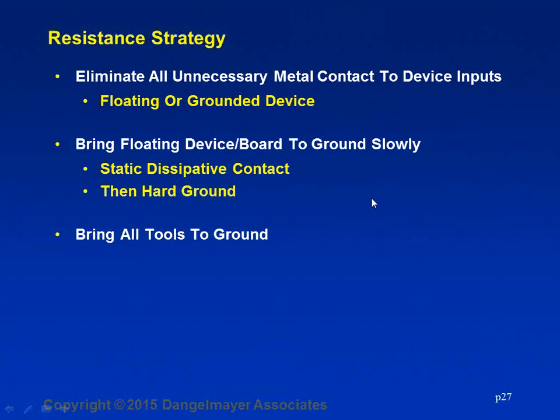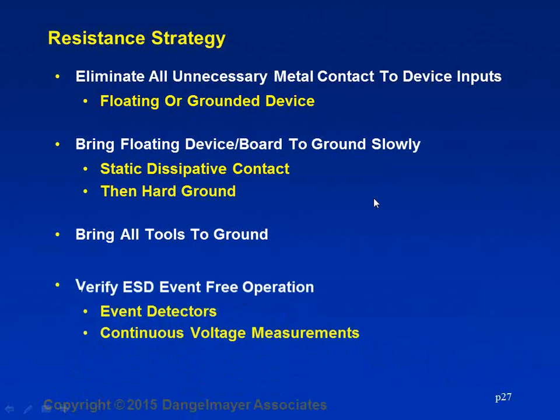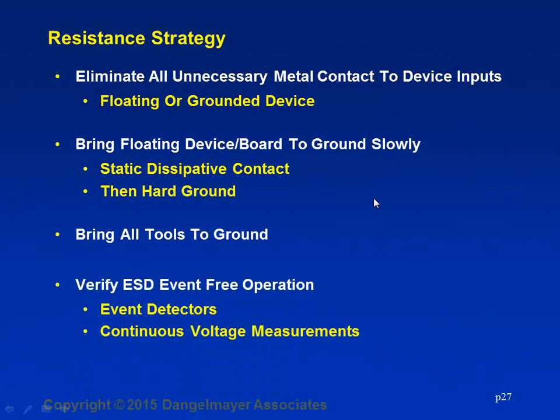Bring all of your tools to ground prior to contact. And then verify all of this is working effectively with ESD event detectors. This is a viable strategy to verify initially and also for ongoing process management to make sure that your product is not being stressed.